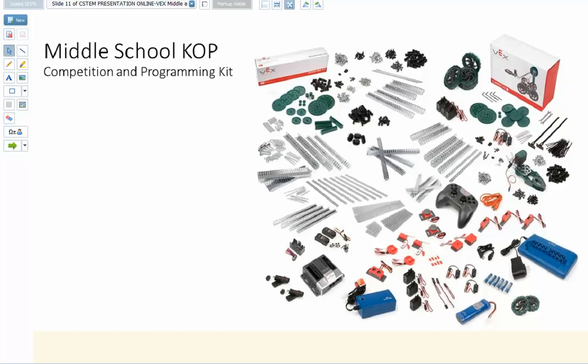Your battery pack, this little blue one here. Anything blue is battery, electronics. Green typically is gears and wheels. VEX, these are your AA batteries. It's always good to have extra batteries on hand and always have them charged. I always have a system set up during competition where as soon as he comes back, plug him back in there and charge him. Very good tip.